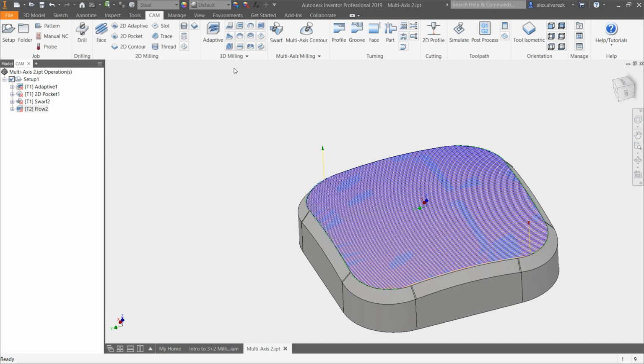Yeah, and the reason they wouldn't attach the code is because, again, we have this toolpath here, right? And you can essentially program it on dozens of different machines, right? So the code is not always going to be the same. So that's why they don't necessarily attach the code to the part. Yeah, the code's not attached to the part, but the setup is attached to the part. Setup and the toolpaths are always going to be there. Yeah, because once you hit that post process, you have the ability to export into a million different posts. Not a million, it's a couple thousand, I think. But anyways,